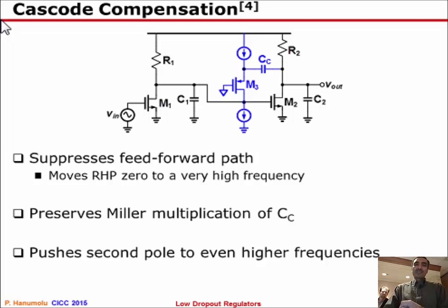So, which one works better? Well, in many cases, you only can make the loop bandwidth faster, but if you already know that your digital logic is going to switch now, and if you can give me like few tens of nanoseconds advance notice, then you can also prepare the LDO to be ready by assisting the LDO to supply instantaneous currents at startup or power on.